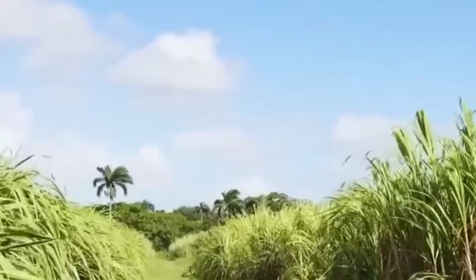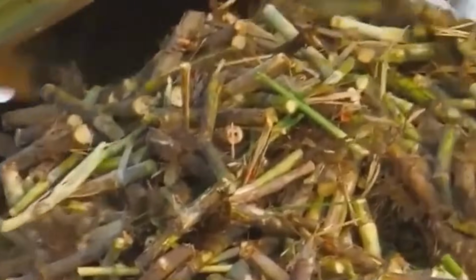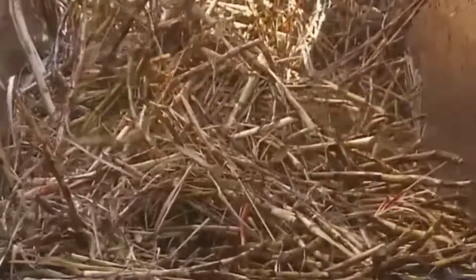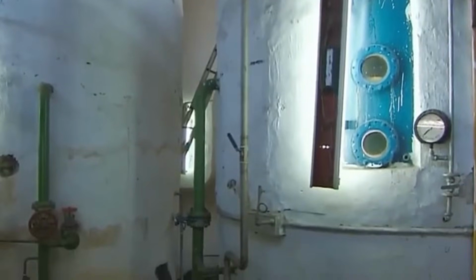Packaging begins with slug loading. Cookies are grouped into vertical stacks, or horizontal slugs using indexing belts and pushers. Slug formation is synchronized with wrapper film feed using registration marks and encoder-driven rollers.